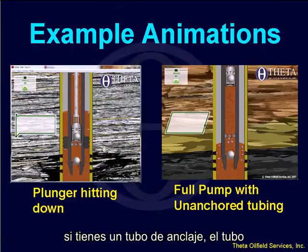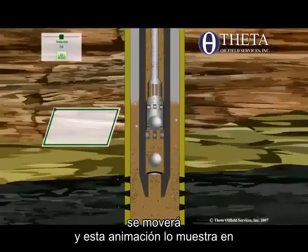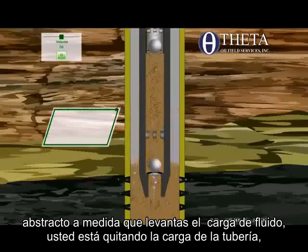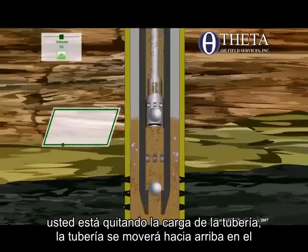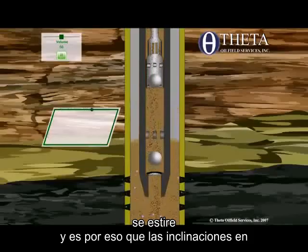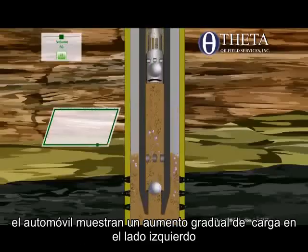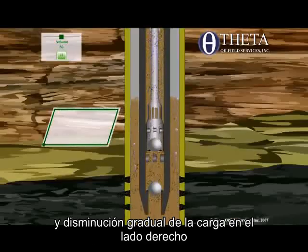If you have unanchored tubing, the tubing is going to move. And this animation shows that. So in the upstroke, as you pick up the fluid load, you're taking the load off the tubing, so the tubing is going to move up. On the downstroke, you're putting load back on the tubing, so the tubing will stretch. And that's why you have the slants on the cards, showing gradual increase of load on the left side and gradual decrease of load on the right side.